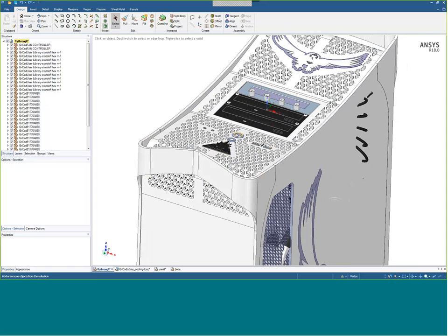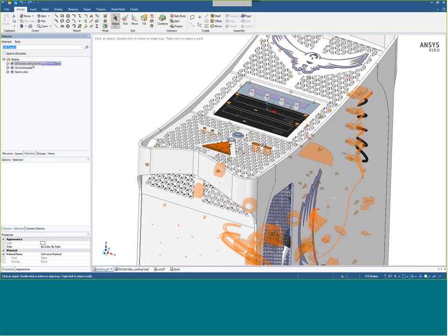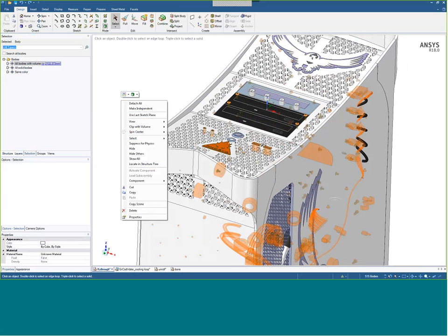The other thing I wanted to point out, again for people that might have missed it: if I start to select one thing, and I want to find all things that are small, or get all the really tiny things in the model, and I do not want to include these in my physics, I right-click and choose suppress for physics.